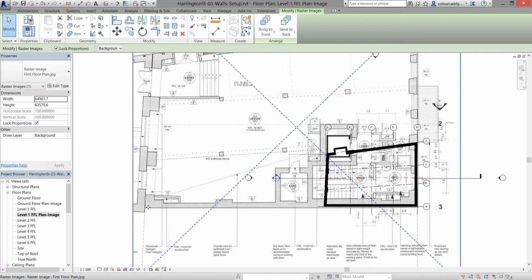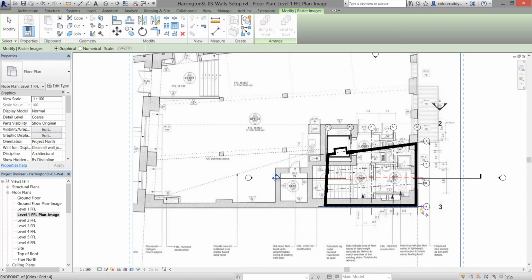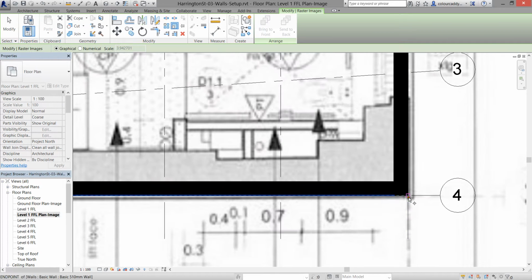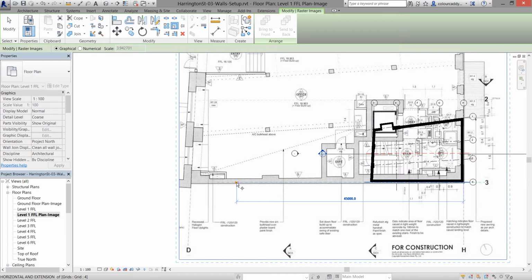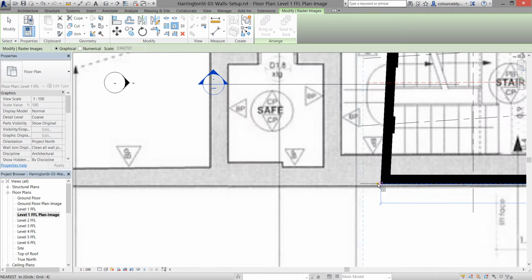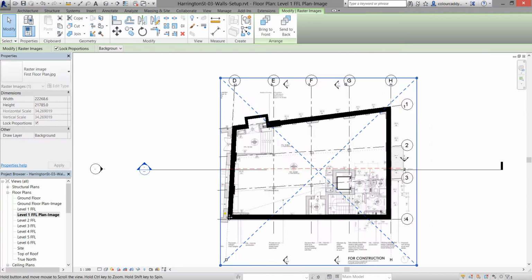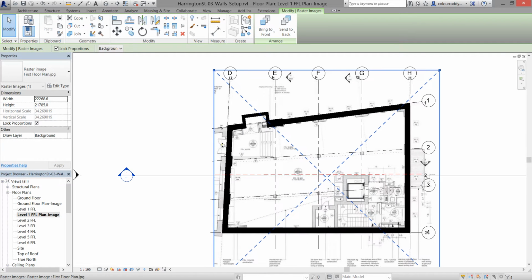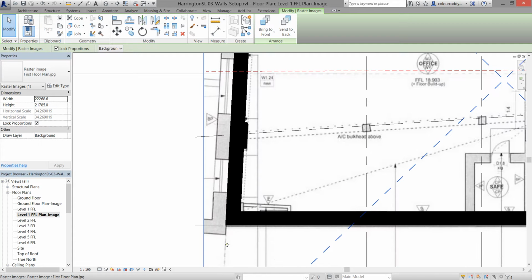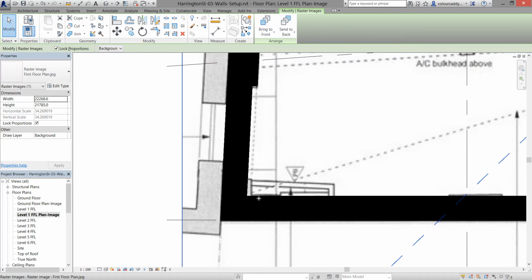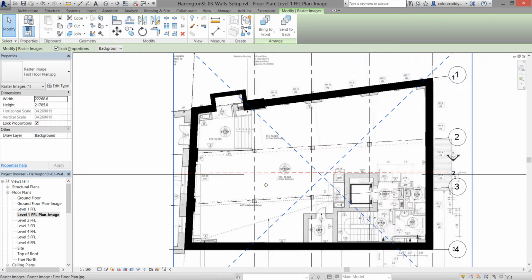that whole wall on the image, and again still with that image file selected I'm going to click the Scale tool. So I'm going to click a point again on that corner. This time my second point I will click on the other end of that wall, and now I'm going to bring it back, and the third point I'm going to click onto the corner of the wall that I've drawn in Revit again. So you can see how that lines up fairly well, maybe a little bit low, so I'm just going to use the arrow key to try and nudge that up a little bit so that it lines up. And there we go, that's close enough.